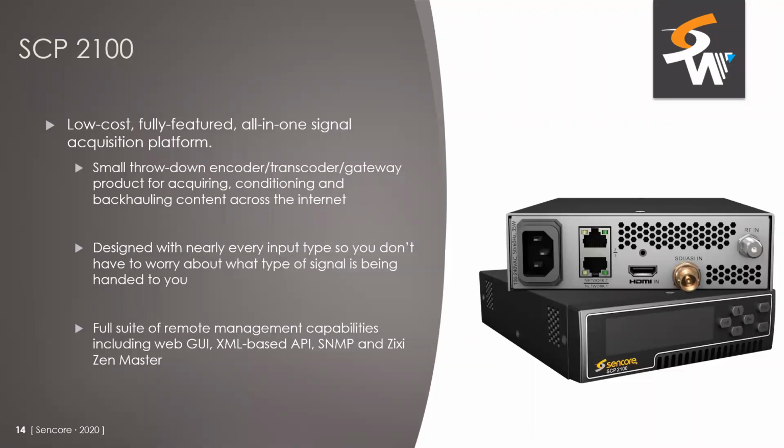And based on that, you can either do your encoding if it's SDI, or do some transcoding in the case of ASI, or maybe you just want to pick off a couple of the services, or maybe change the PIDs or service numbers and send the entire thing out. You can do all of that on that ASI signal. So it's designed to be very easy, that anyone on site can plug in what fits, so to say, and the device will figure that out, and then you can do the applicable processing that you want on there.